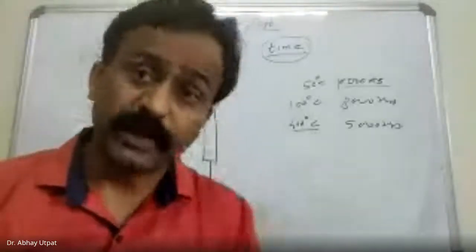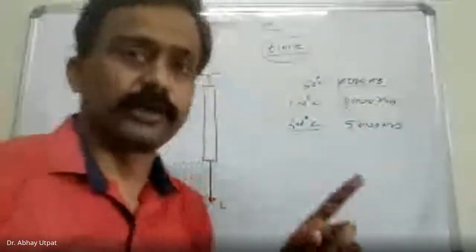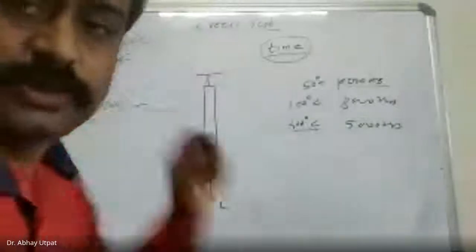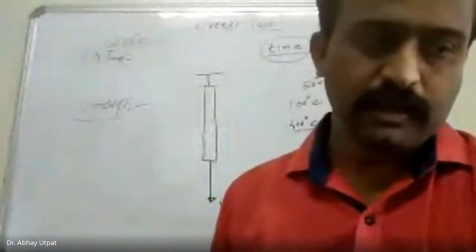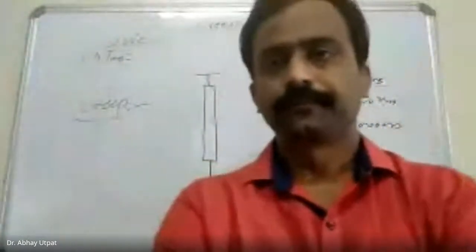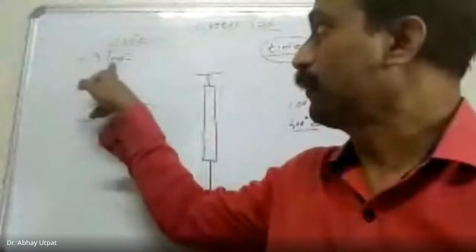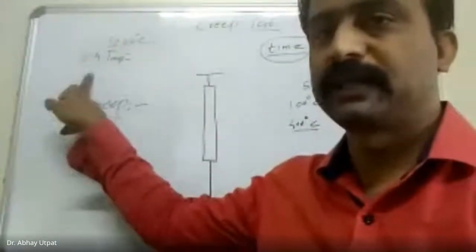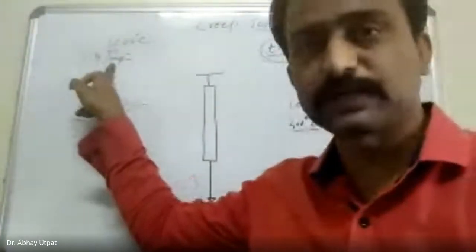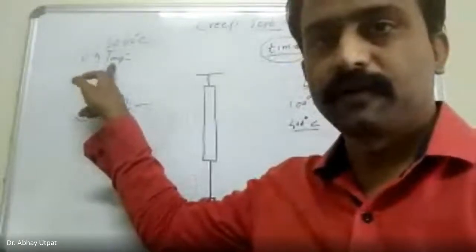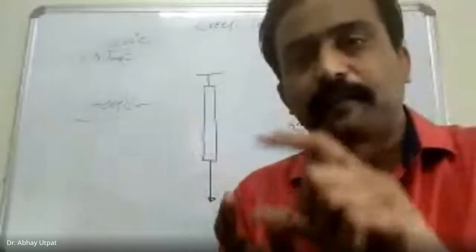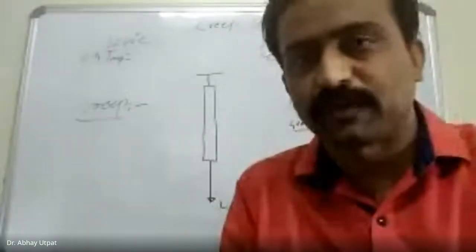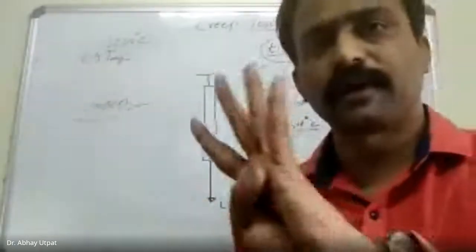Now in bracket you write down this. This means what? Write down, temperature constant means what? Approximately above 0.4 TMP. T stands for temperature, MP stands for melting point. Means whenever you want to observe the experiment, you must see that temperature is, suppose melting point is 1000, what is 0.4 TMP? 400.